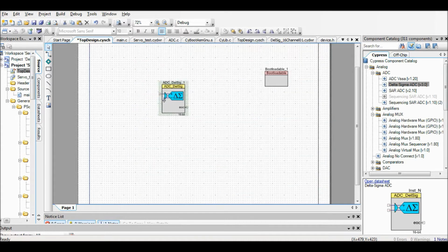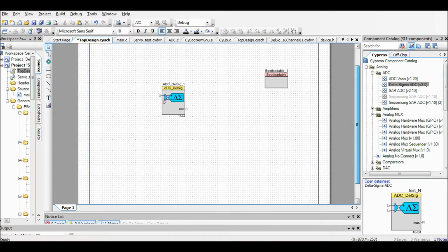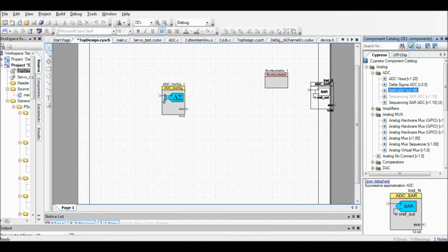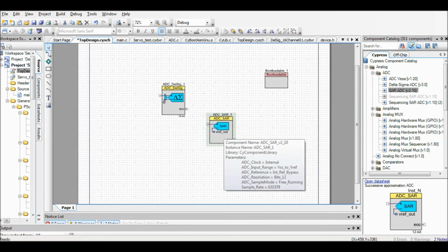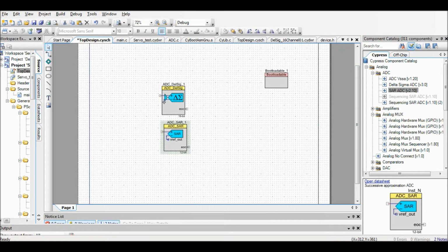Easy enough. So as I just said, we're going to do this with a multiplexer to make this a 2-channel ADC to read both analog values. You could alternatively just use another ADC. Just drop it in. That would be equally fine, and then just one of them takes care of the X axis reading, one of them takes care of the Y axis reading. But I'd like to, for purposes of demonstration, show you another way to do it.